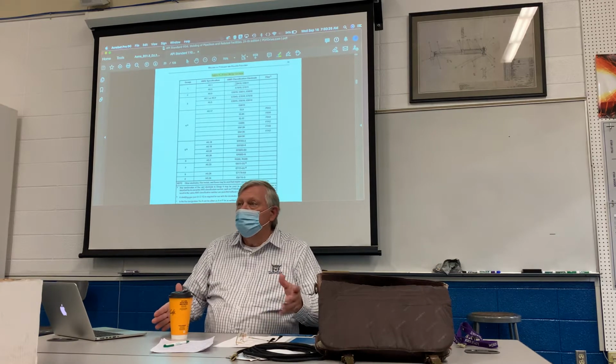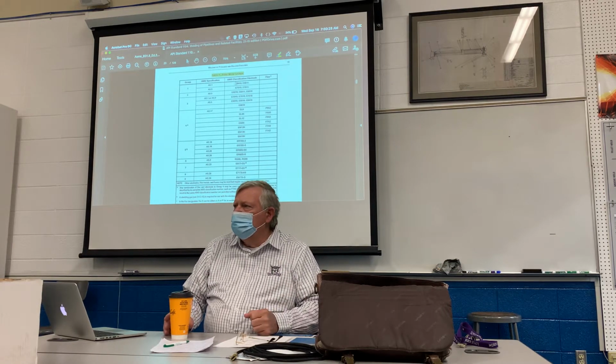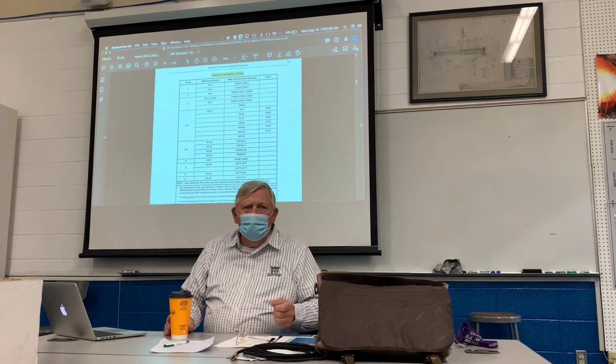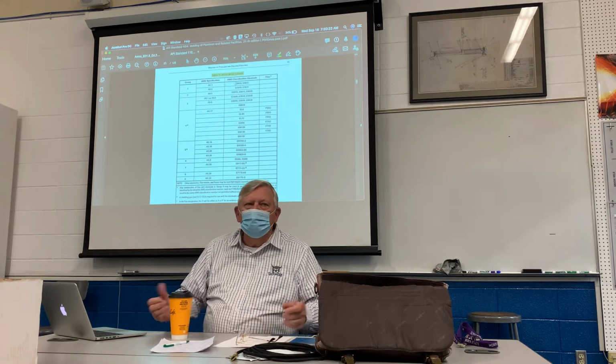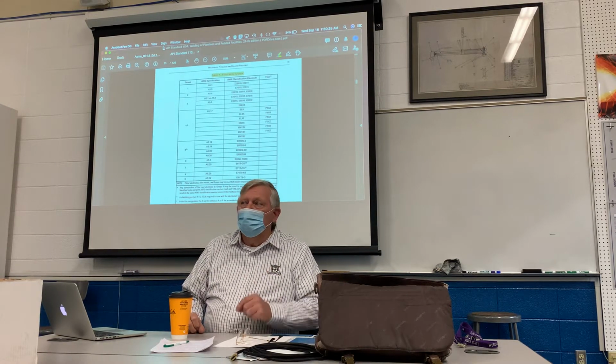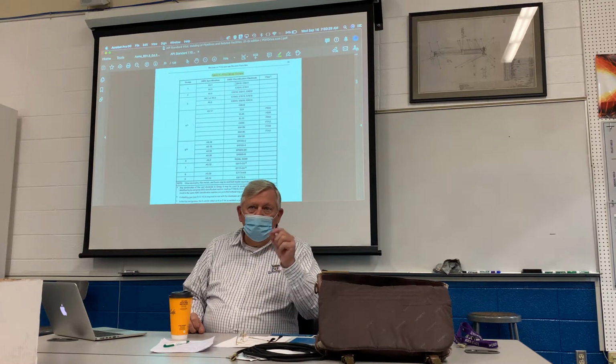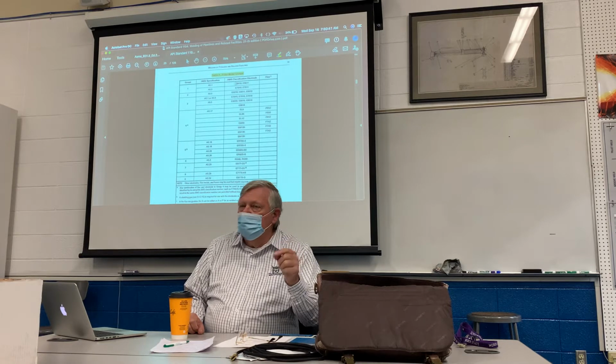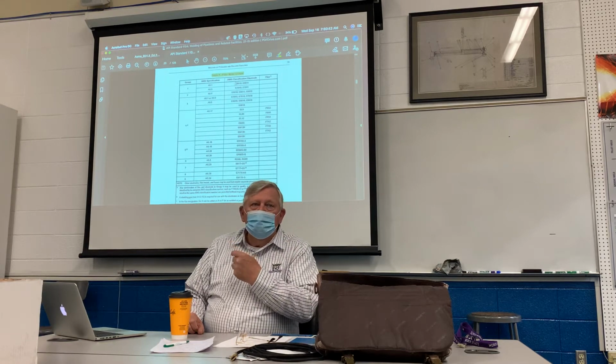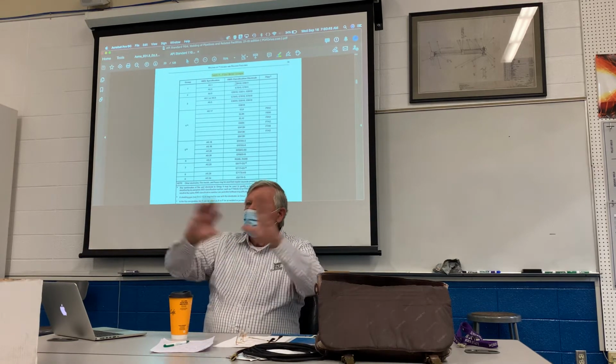You ever worked with AC? It's terrible to run. It's really hard to keep lit and welding. You have to keep turning the heat up, so the weld becomes inferior. Well, to solve the problem, they just redesigned the electrode. And they put a different coating on the electrode, and they changed the steel a little bit, and they called it 6011. And they sold it to all these farmers all across the country.